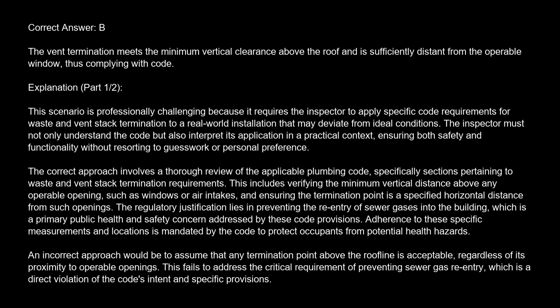An incorrect approach would be to assume that any termination point above the roofline is acceptable, regardless of its proximity to operable openings. This fails to address the critical requirement of preventing sewer gas re-entry, which is a direct violation of the code's intent and specific provisions.